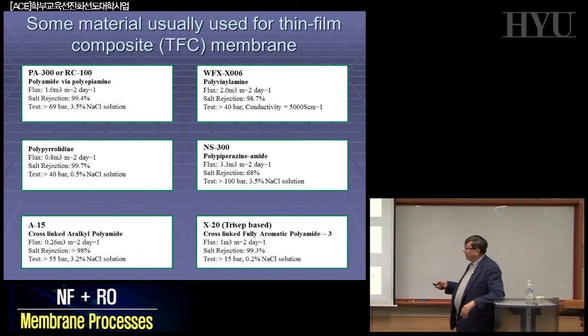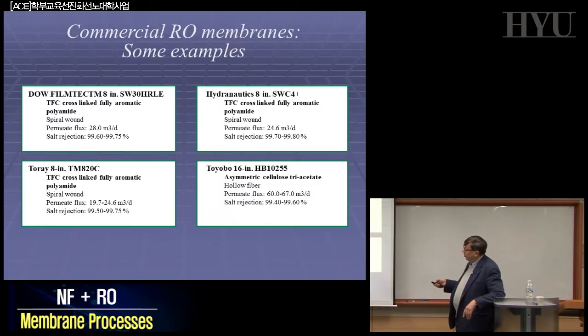Which means that some of these membranes designed only for chlorine resistance are not so important anymore. On the other side, you can see basically that polyamide, aromatic polyamide, are also, this one is also an aromatic polyamide by the way, but they are the ones that are more used. And all of them can be produced in flat sheet and organized in spiral wound modules.